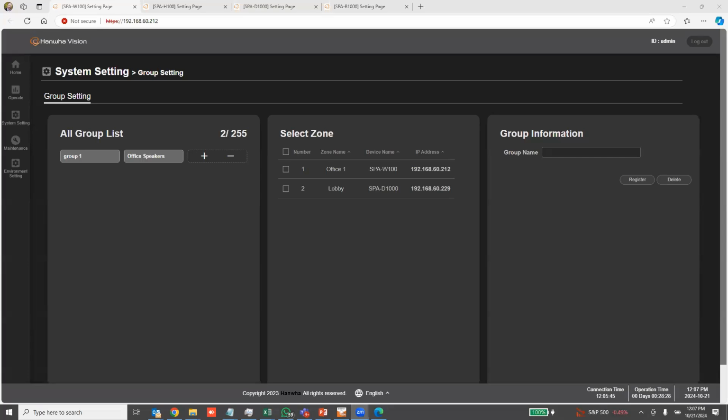So for Jeff, with Wave or Wave Sync, either way, yes, if you wanted to trigger an audio message, we would have to go to our knowledge base. There's a step-by-step, 3 or 4 steps you've got to do. You would create a soft trigger in the event engine, and that soft trigger would then play a pre-recorded file out of a speaker or a group of speakers. And again, happy to chat with you later. I can show you how to do that.